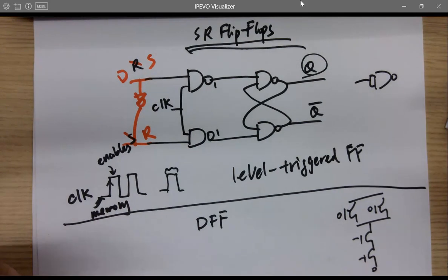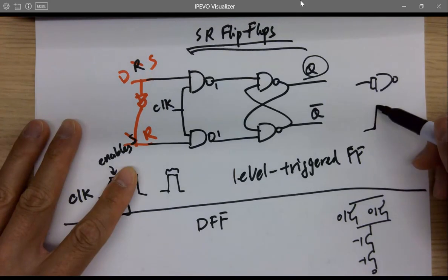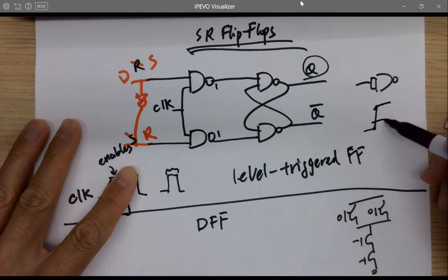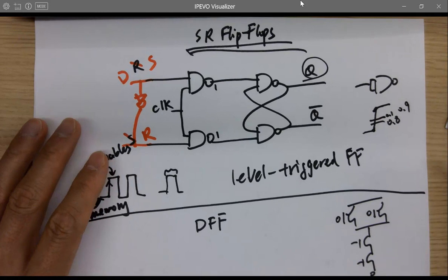Is that because the holes are, let's see. So one of the reasons is probably the threshold voltage is higher. So whenever it starts from 0 to high, right? At 0.8 volts, NMOS is already on. But for PMOS, it has to wait for another 0.1 volts rising time because PMOS has a higher threshold voltage.